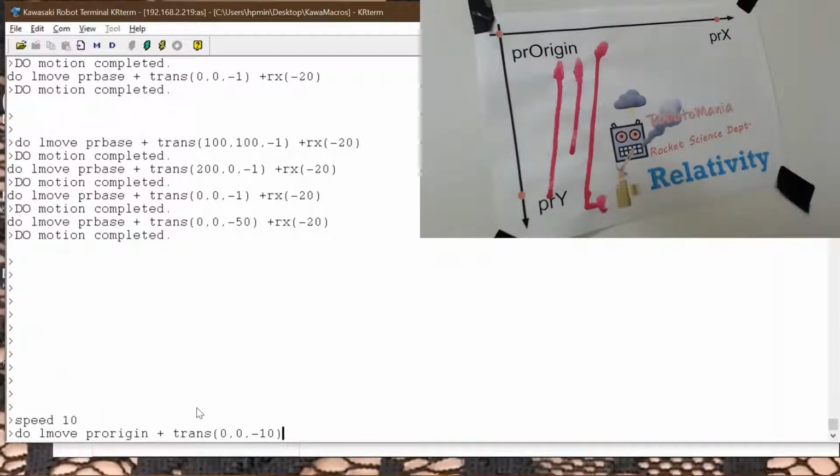Now this is very important to understand. This portion is not operated anymore in the base coordinate system of the robot, where Z is vertical, X is toward you, Y maybe somewhere else. It operates in the tool coordinate system of the hand at the present position just before this sign. That's very important to understand.